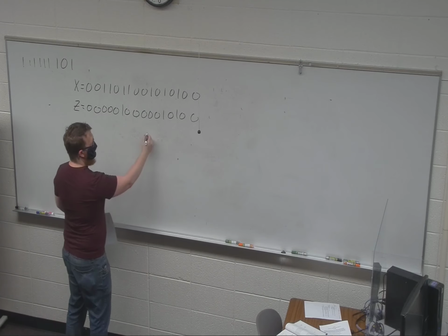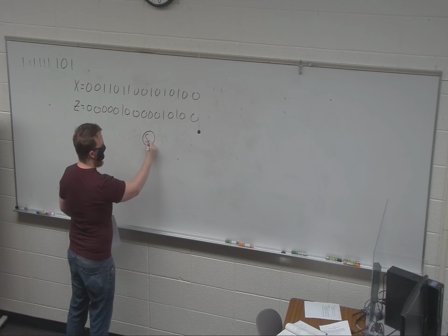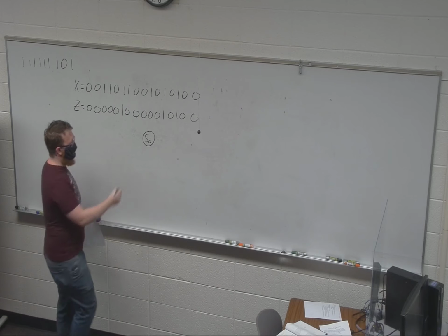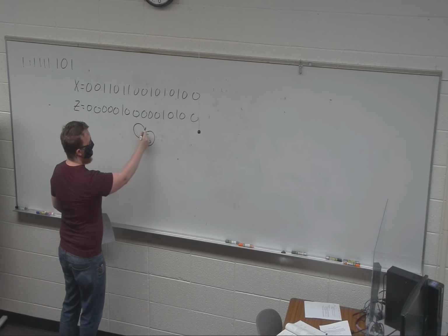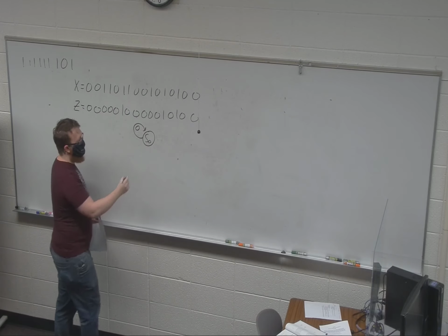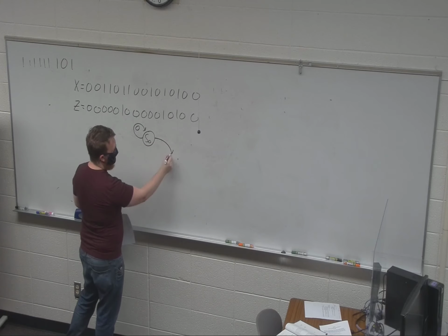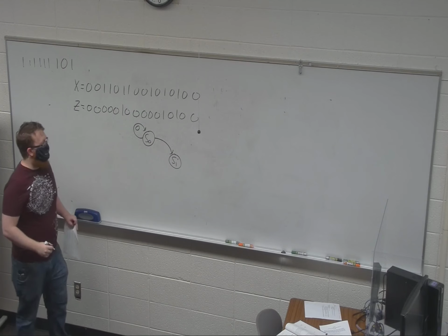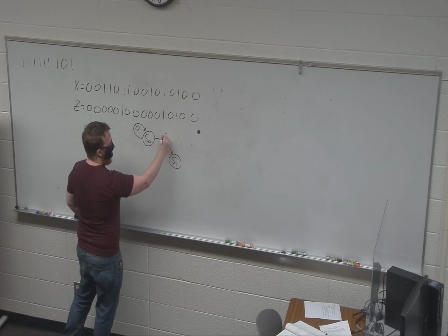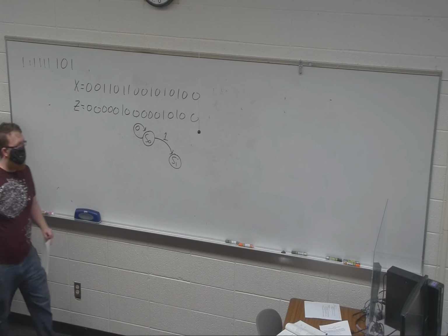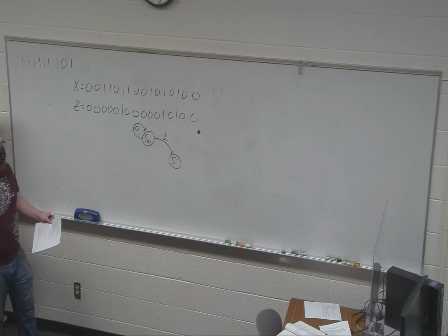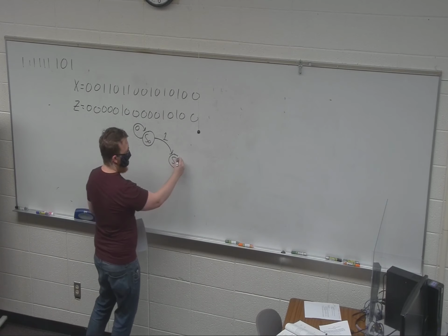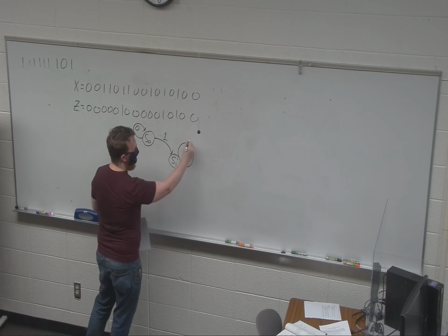Okay, so the Moore state machine, obviously we're going to start at state 0. There's not a lot else we can do. And it's going to do the same thing. We know that if we see a 0, we just don't care. And we know if we see a 1, we have to go to another state. So if we didn't, nothing interesting would happen. So this happens if we see a 1. Right? So now we're back in the same boat. If we see a 0, if we see a 1, well, it could be the same thing.